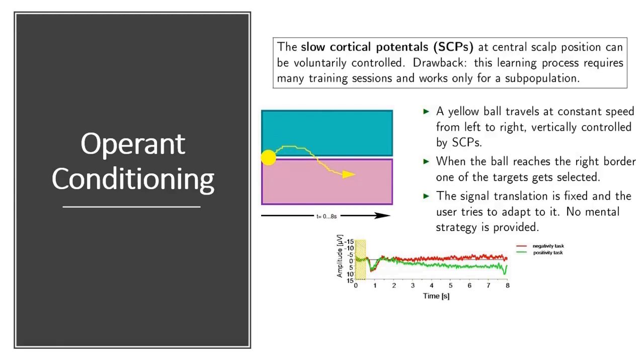This type of endogenous BCI can be used to control external applications, usually with a binary command. However, this is a very classical early version of the brain-computer interface that doesn't rely on any advanced, sophisticated signal processing or machine learning algorithms. However, it requires the human to train himself. Training himself is equivalent to establishing some kind of neuronal network in your brain, or basically training your brain to generate some specific signal patterns or slow cortical potentials.